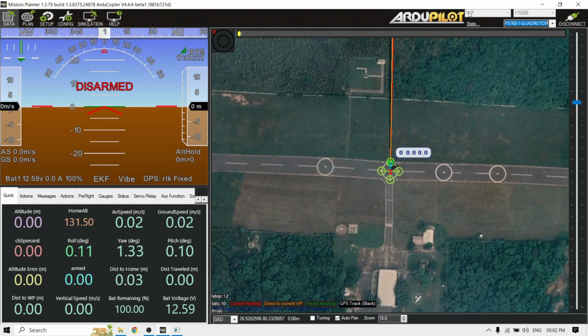If you connect using some normal telemetries, then you might get com ports. So basically we would be getting COM4, COM5, COM6, whatever the respective comms you would be getting. This is baud rate. As of now you are getting this baud rate for the default Wi-Fi, and you can change this, but as of now these are the standards which the simulator permits, so this is constant, no need to worry about that. But when you connect the normal telemetries, the serial based or com port based, then the default would be maybe 57600 or something like that. And this is the drone TCP at port number 5760. This is my drone that's being connected.